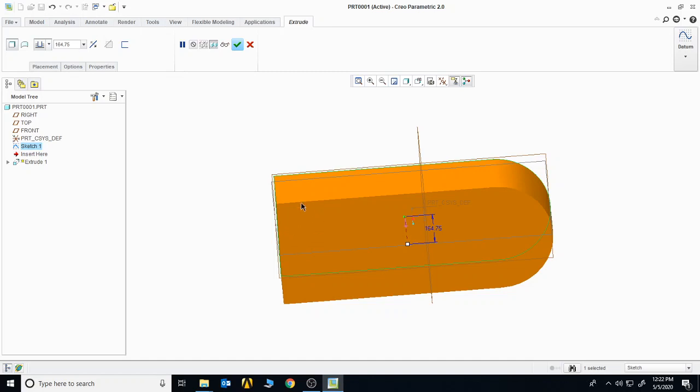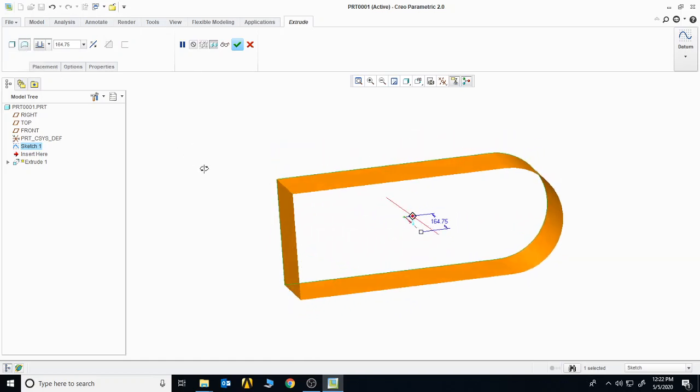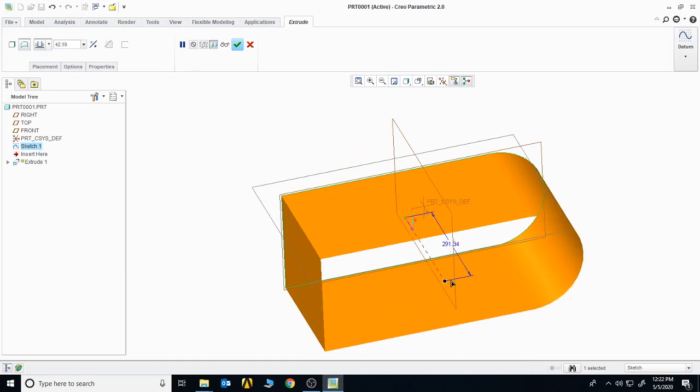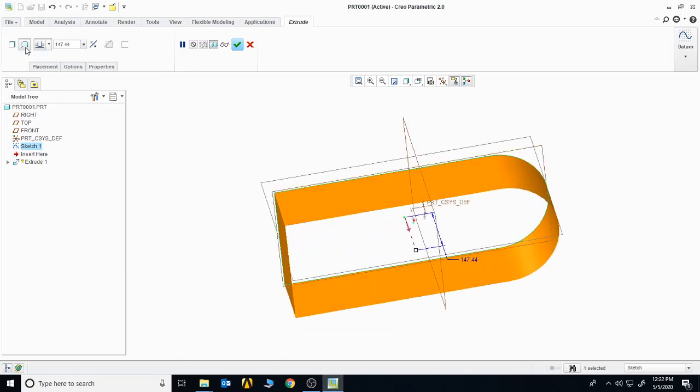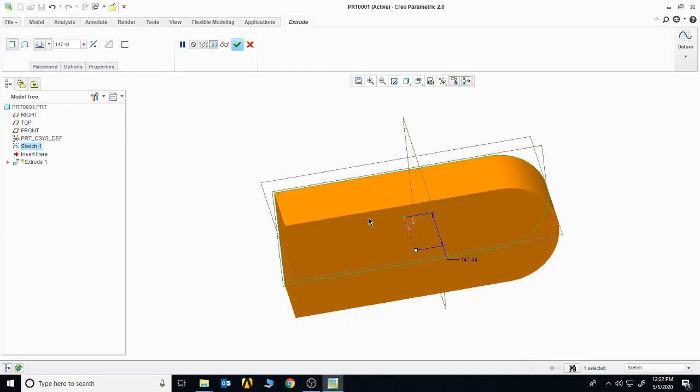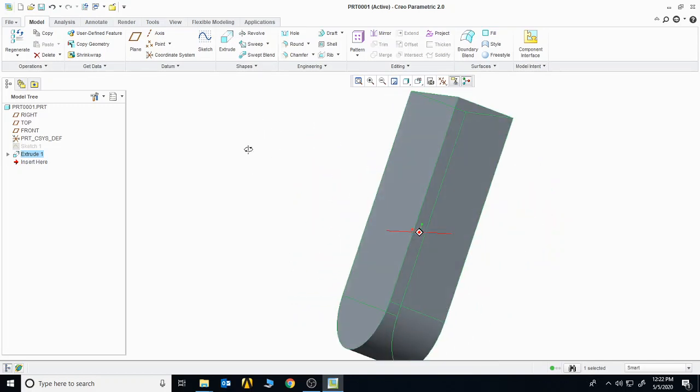If you want to extrude it as a surface, click here on extrude as surface. So it will get extruded as a surface and again you can define the height of it. So you have got both the options if you want to extrude it as a surface or if you want to extrude it as the solid. If you want to get it done, so click on the OK and the changes you have made will be saved. So this is what you have generated.